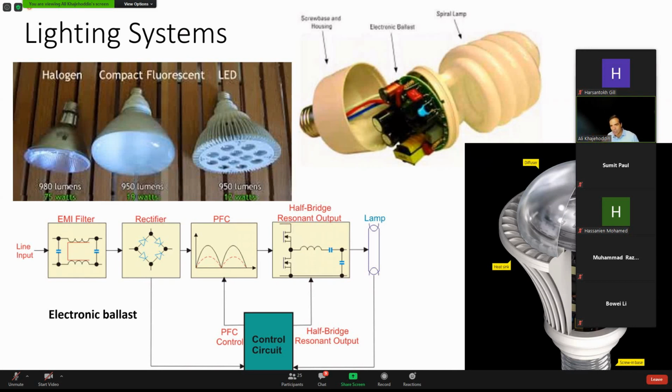the converter has to be very simple but very reliable, and also operate in a very harsh environment, small and hot, just because it's very close to the lamp itself or to LED arrays. This is again another explanation of how this converter is running or driving this lamp. As you know, you need a high voltage here, but at the same time you need, especially for lamps, very nice low harmonic current.